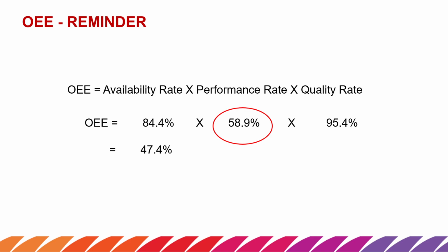That is OEE, Overall Equipment Efficiency. OEE is the product of three KPIs: availability rate, performance rate, and quality rate. Availability is the time for how much machine was available for production. Like in this availability, we calculate the breakdowns that have made machine unavailable for production.